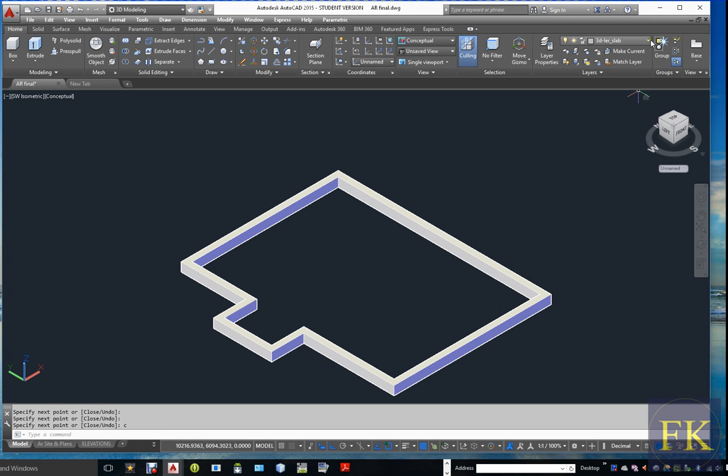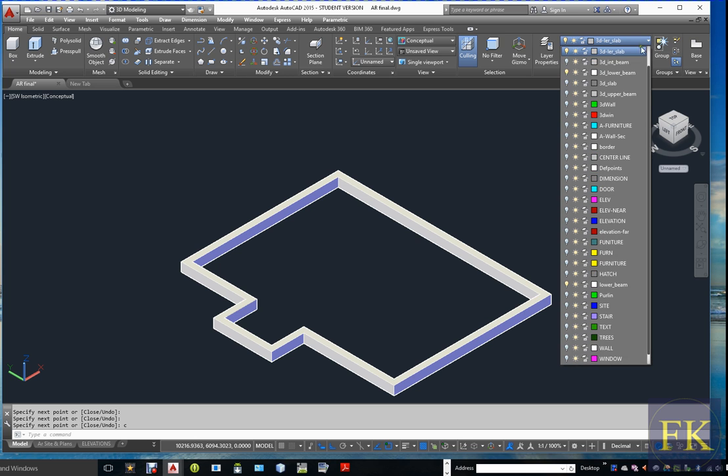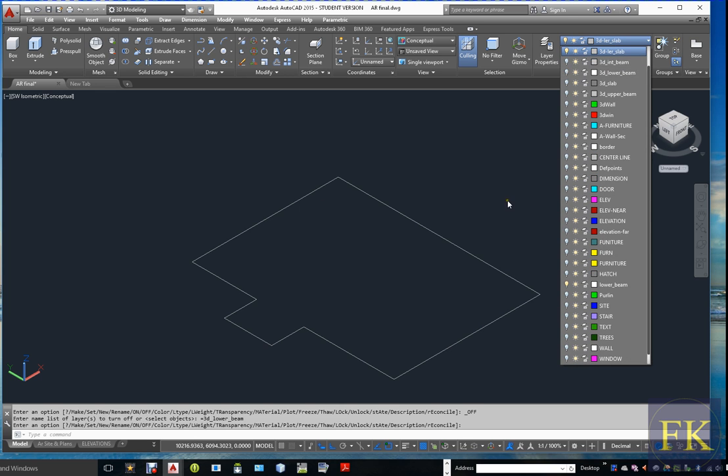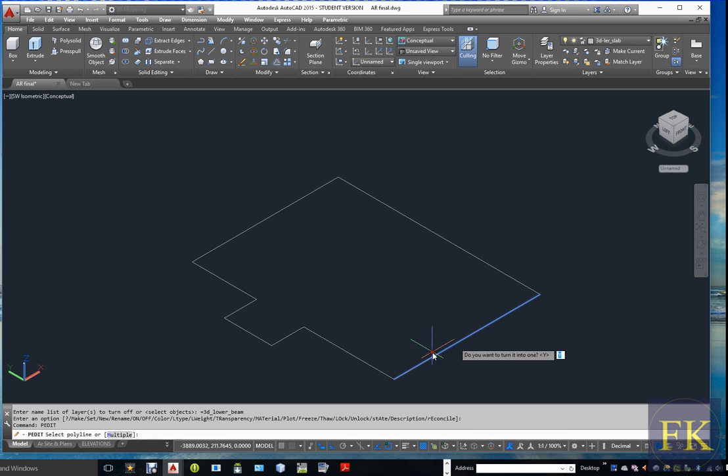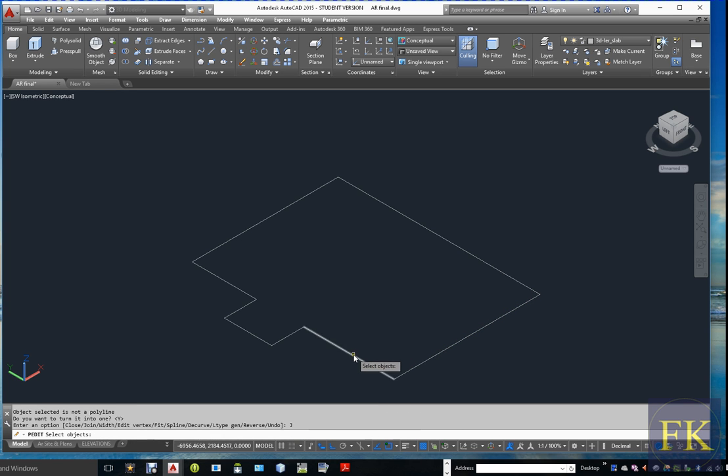Okay, now let me turn off the lower beam. Okay, and then I'm gonna pedit these lines, join, yes, join, join, join, join, join, enter.